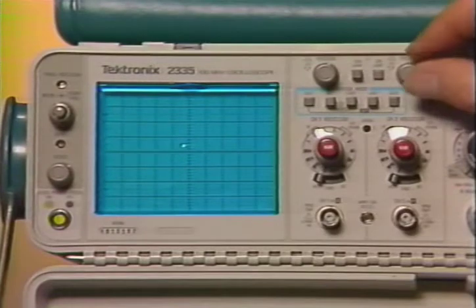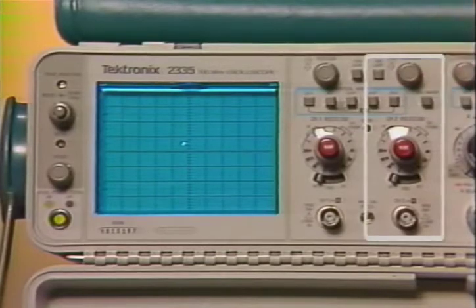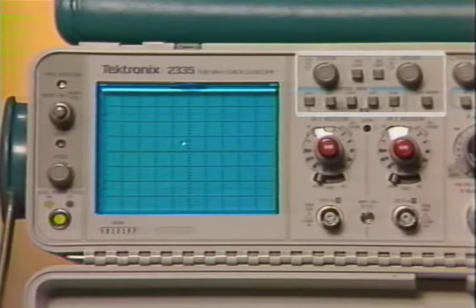The vertical system controls movement in what's called the y-axis. Y signal information is applied through calibrated attenuators and an amplifier called a channel. The vertical system also has position controls and ways of selecting and combining 2 channels.